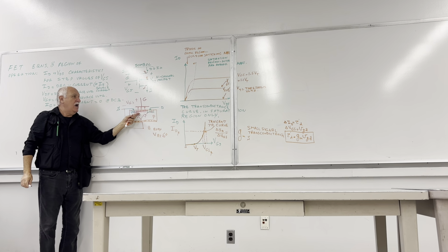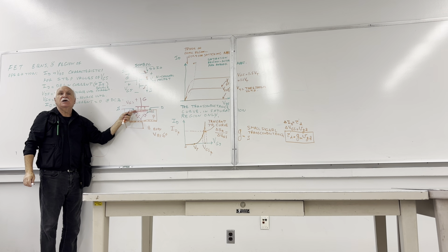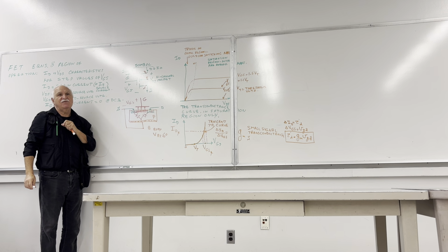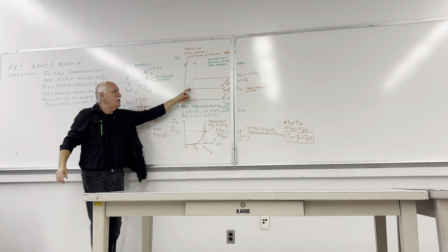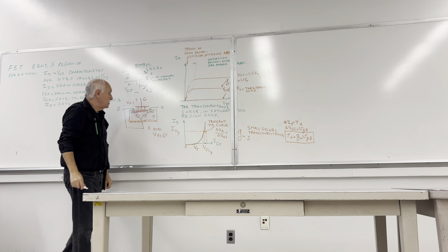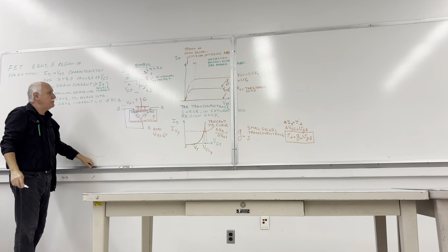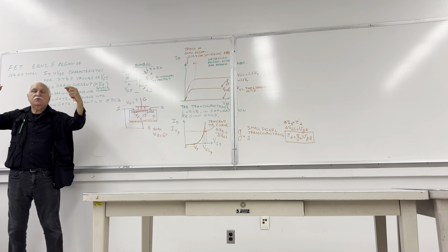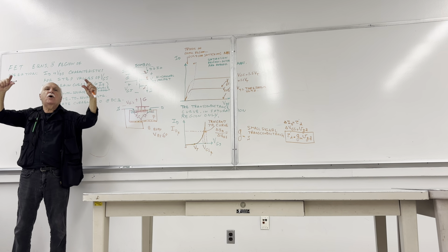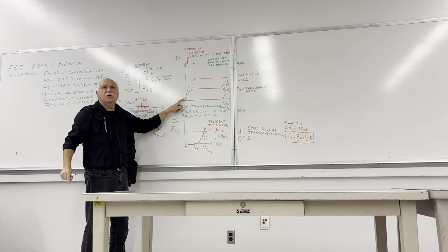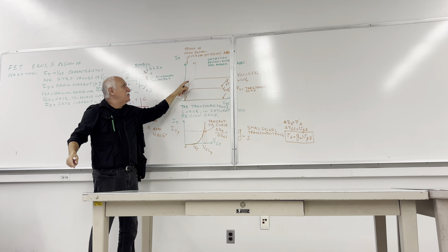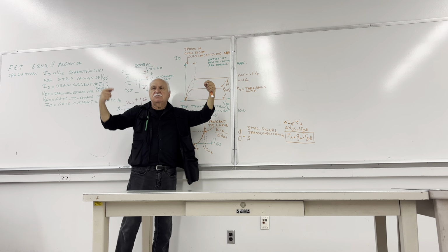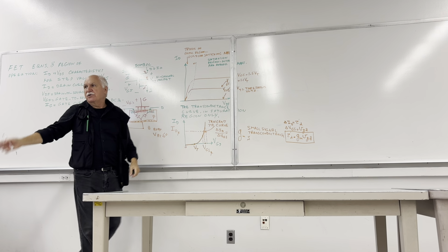Tapers, and as a result, we will get less conductivity, less mobile electrons available there. Therefore, the current will reach its saturation, leveling over there. That's the nature of semiconductors. Semiconductors, when you pass a current, like one bar, they look like a resistor here initially. You put more voltage on it, their current will increase, but eventually will flatten at some point. There will be no more extra current.